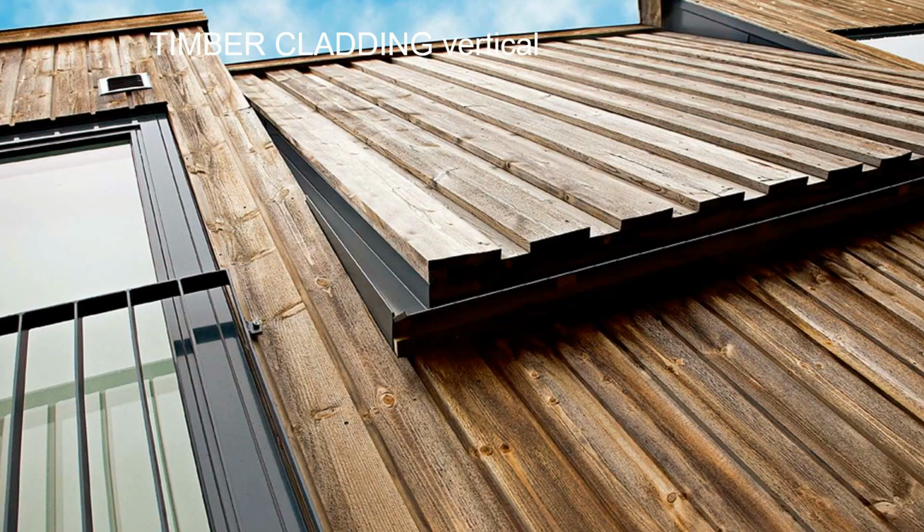Vertical cladding is a little bit different, and usually in Scotland we're talking about a variation of board-on-board cladding. So it's front boards and back boards. So we find that we've got a board here that we can see going upwards, and then behind that there'll be another board, and the same to the other side. And these boards will be nailed through. There's a nail there and there's another one there.